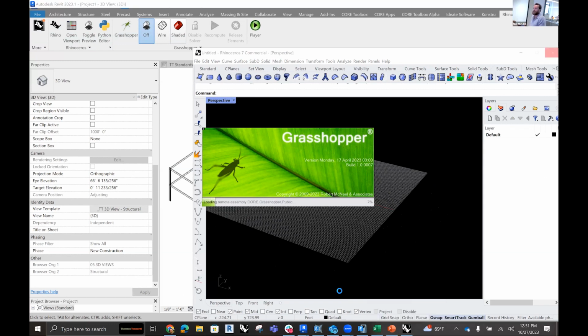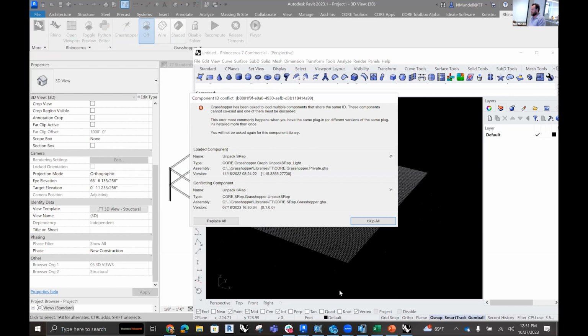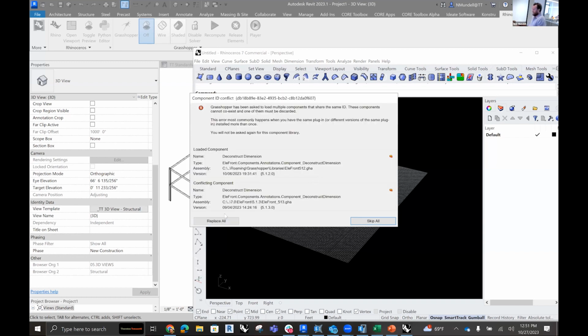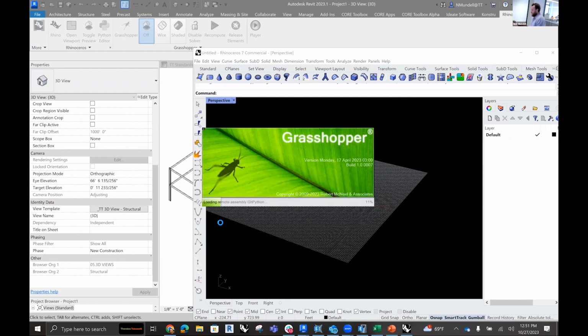And I guess what I'm proposing here is that if you find yourself in a place where you need to compare your SAP model to a Revit model, you don't necessarily need to use Konstru and upload and do the merging interface I showed previously. You can literally upload your SAP model to Konstru, download it to a Rhino inside Revit instance, and then you have the model overlaid directly with the Revit model. I'll show that in a minute once we get loaded in here.